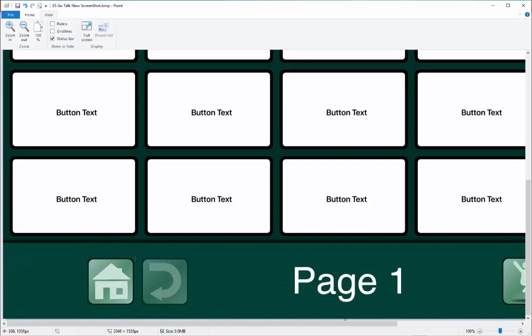And then I need to calculate what is the height and width of each of these buttons, and they look to be the same, so I can use the same value for both of them. But what I'll do is I'll go up to this corner and get the X and Y location here. And it's approximately 392 in the X direction. So all I do is subtract 252 from 392, because 252 is what it was down here. Up here it's 392, and that gives me a nice value of about 139 pixels wide.